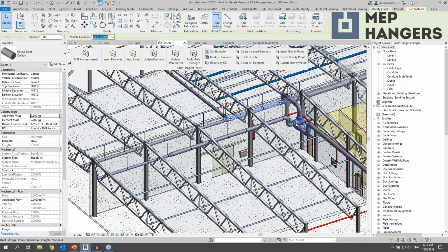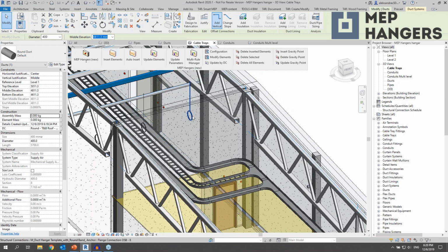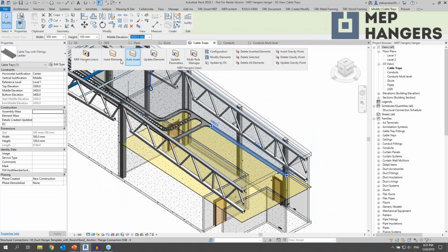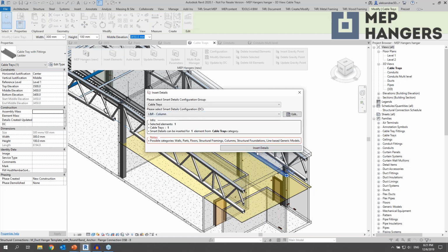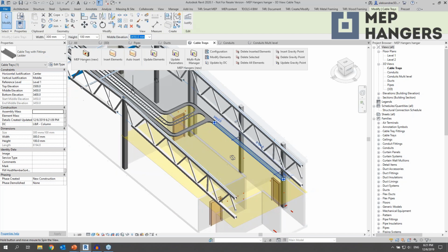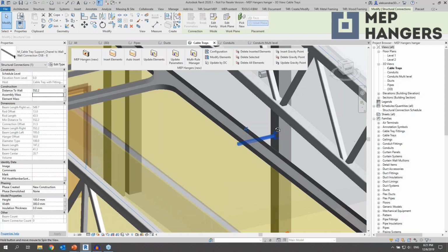And that's the possibility. And here ducts are turned off and we can see that only hangers are visible. With cable trays, works exactly the same rules, left and right, column, insert will connect to the column with the hangers which were loaded for cable tray.